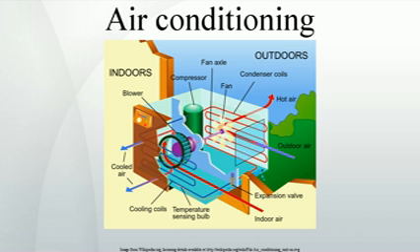Those enclosures can be painted to match the color of the house. The primary disadvantage of ductless air conditioners is their cost. Such systems cost about $1,500 to $2,000 per ton, 12,000 British thermal units per hour, of cooling capacity. This is about 30% more than central systems, not including ductwork, and may cost more than twice as much as window units of similar capacity.